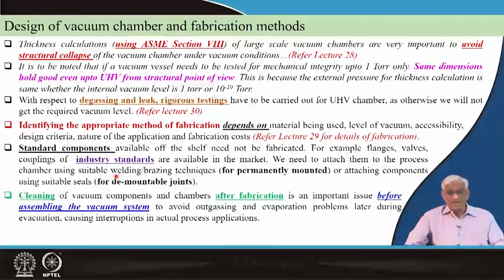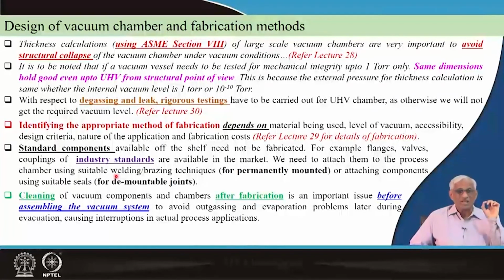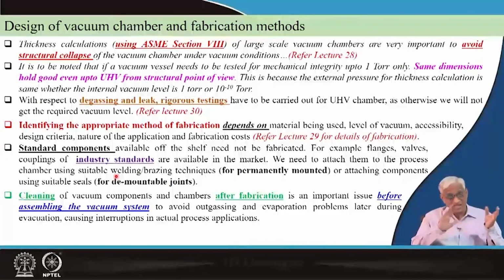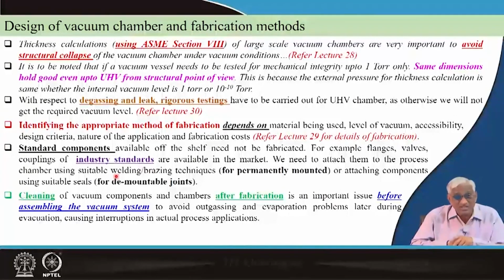Then cleaning also is a designed cleaning, whether you can use water cleaning or soap water or carbon tetrachloride or some other special cleaning agent or purging of the gas. If you are purging that gas load, who will remove it later? You have to purge means fill it and again pump it. It takes some finite amount of time. You have to minimize that time. That is the initial preparation. That is a part of the design issue.